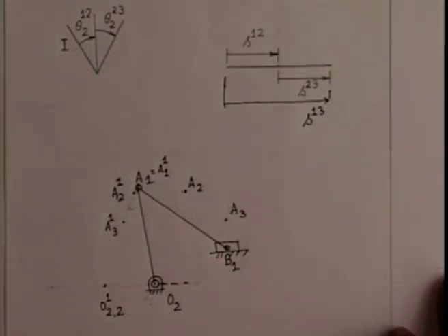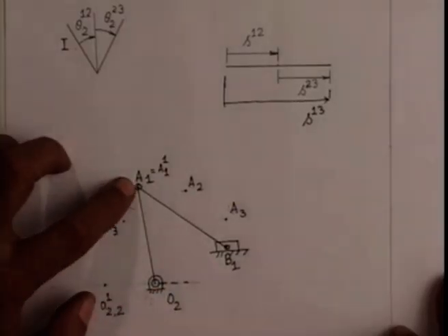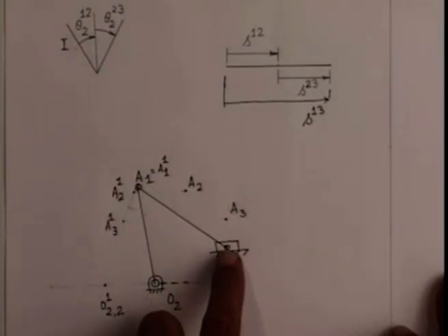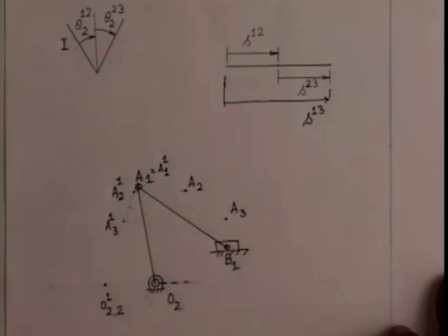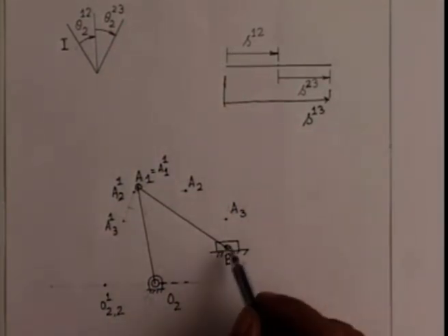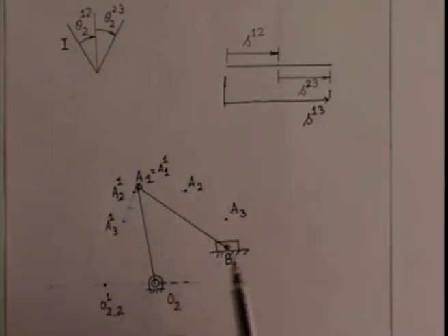As we have seen, we assumed arbitrarily the location of the crankshaft O2 and the crank pin A1. Only determine the slider location corresponding to the first configuration at B1, this revolute pair. We have solved the problem also by choosing arbitrarily B1 and find A1. That is what we will do in the next example.